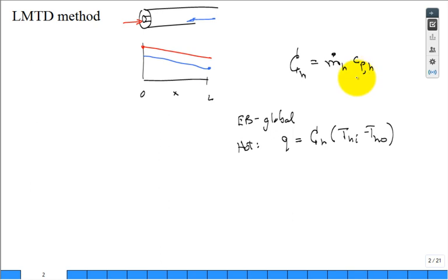Heat capacity rate. Where did this equation come from? Energy balance. Control volume just around the hot fluid. And what is Q? Q is the rate of heat transfer out of the hot fluid. Where is it going? To the cold fluid. We can also write a global energy balance from the perspective of the cold fluid. Now, we don't like to change signs, so Q is both positive out of the hot as well as into the cold.